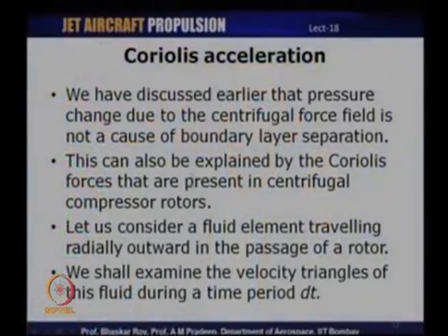In the case of centrifugal compressor rotors, the risk of boundary layer separation is probably lower than that of axial compressors, because the pressure rise is primarily because of the centrifugal force field and not really because of the deceleration of flow.